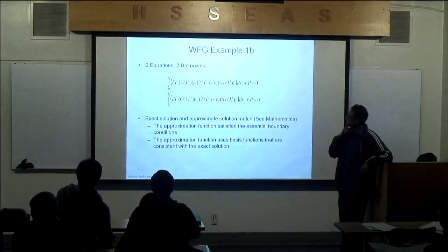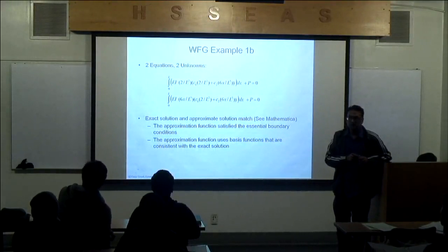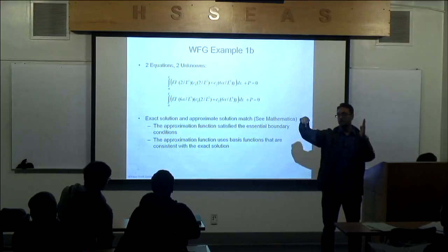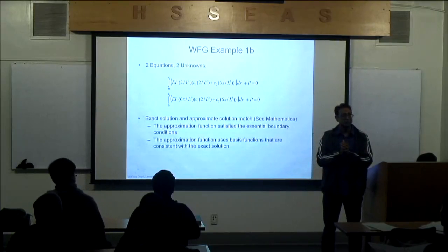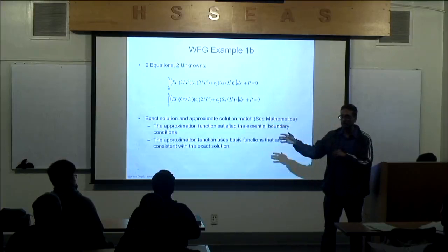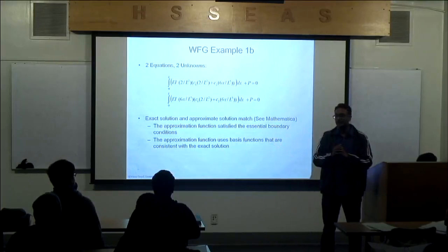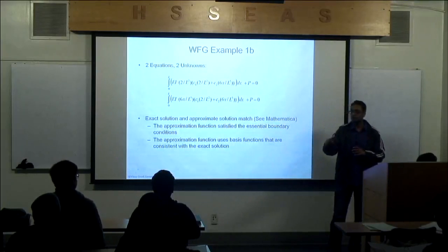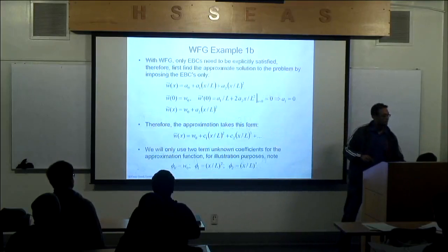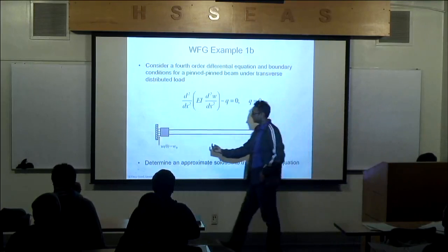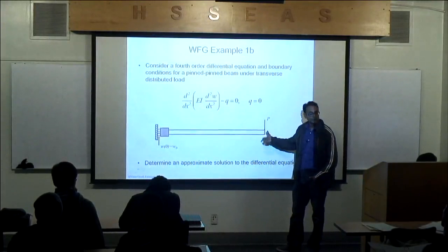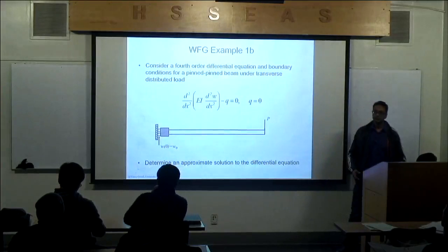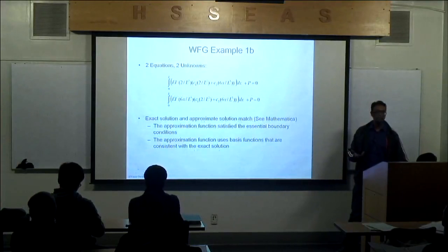It's a great problem because you know the exact solution without doing very much, actually. Anybody know the deflection at the end of a cantilever beam for length L, load P? PL cubed over 3EI. Everybody here should at least memorize one thing, right? PL cubed over 3EI. Well, I got the approximate solution at home, and you do get PL cubed over 3EI, except not quite. You get PL cubed over 3EI minus W naught. Why? I moved the beam upwards W naught, so everything moved W naught a little bit. Then I apply a load P downwards, and so I get PL cubed over 3EI minus W naught. Makes sense, doesn't it? So you can check your solutions to gain confidence in what you're doing.